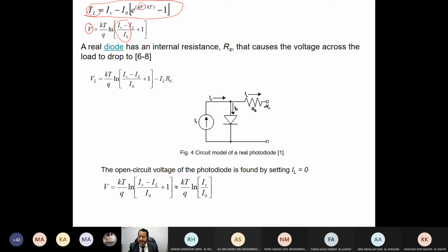The bus bars take the current to the contacts, two contacts at the end. It means the cell, as you can see here, at the end we have P and N, two terminals, positive and negative. This terminal is metal at the end. Inside, fingers and bus bars are metals, so we have losses because they have resistance. Resistance is a property of any material, so we have voltage drop and losses.